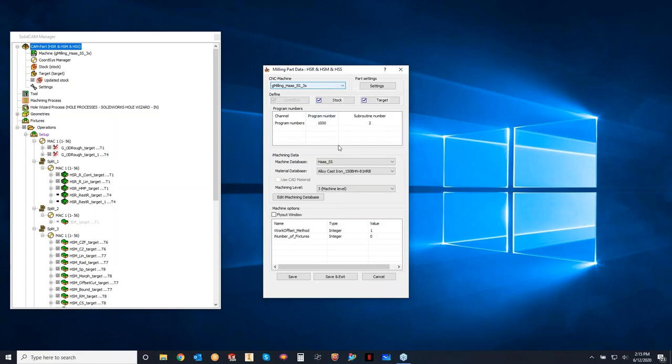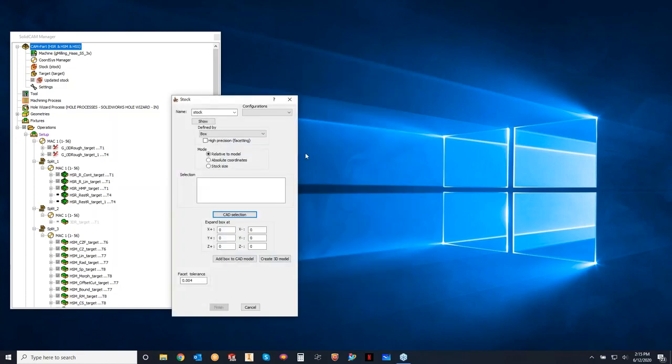If your stock size was modeled with the model box, we can come in here. This one wasn't modeled with the model box, but we can actually come in here and change it. All right, instead of having an additional 100 thou on there, they cut it a little bit shorter. So I'm going to shorten that up to 50 thou for saw cut instead of 100 thou for saw cut.